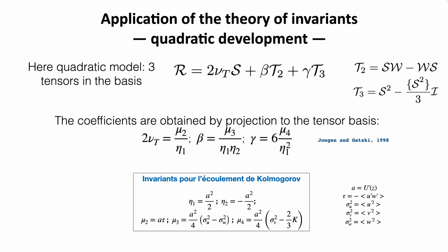Okay. Are there other questions in the seminar room? Yes, there is one. So you said that the hypothesis failed when there is no strong gradient. So in wall turbulence, for example in channel flow, do you think that this is the main reason why the modeling with the Boussinesq hypothesis fails, or is it because of the region where it works but doesn't work perfectly? Because it is in the center of the channel that you have this failure, but do you think that this failure of the hypothesis in the center of the channel affects the full mean profile, or is it more due to what happens near the wall?